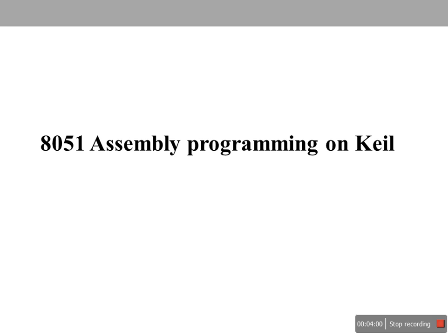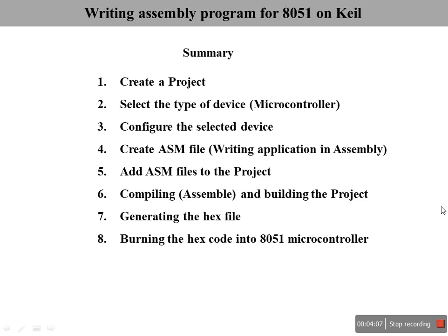Yes, let's go with assembly language programming and Keil software. Look at this very carefully. I'll summarize what has to be done to program 8051 on Keil. The first step is to create a project on Keil software. After creating a project, you have to select the device that you want to program. Since the Keil IDE supports a lot of microcontroller and microprocessor devices, we have to select which one we will be working with. Here we'll be selecting the 8051 microcontroller.